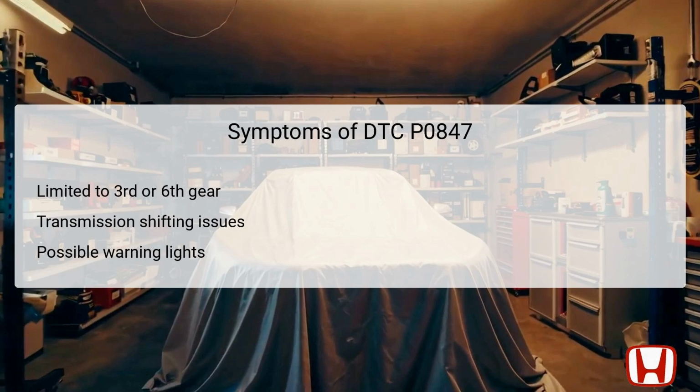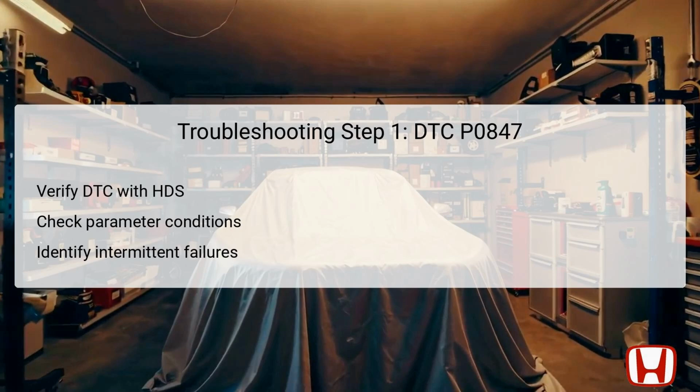Indicating a problem that requires immediate attention. Recognizing these symptoms early is critical in taking steps towards rectifying the issue and maintaining vehicle operation safety. The first step in troubleshooting DTC P0847 involves utilizing the Honda Diagnostics System HDS to verify the stored DTC.